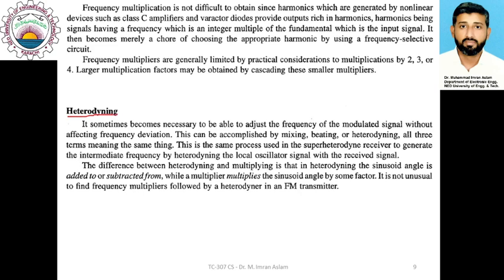In addition to frequency multiplying, there is another important term which is heterodyning, which we have also previously used in the discussion of AM modulation. The term heterodyning refers to frequency mixing where you either add or subtract the frequency. Heterodyning actually creates the multiplication of 2 frequencies, and eventually when you expand those you get the sum of frequencies and the difference of frequencies. And by appropriate filtering,